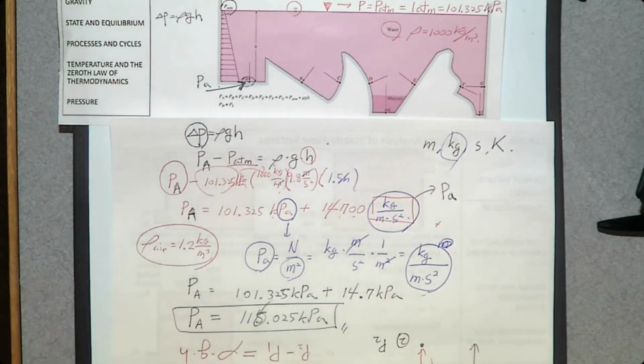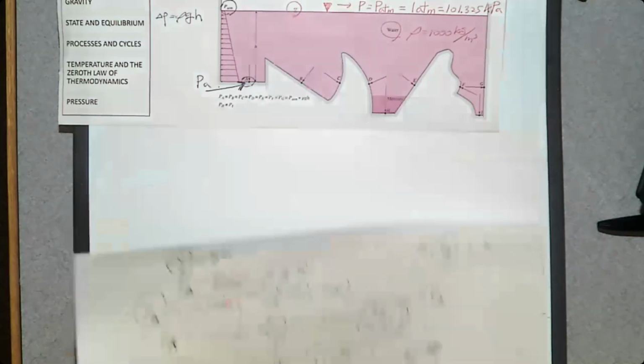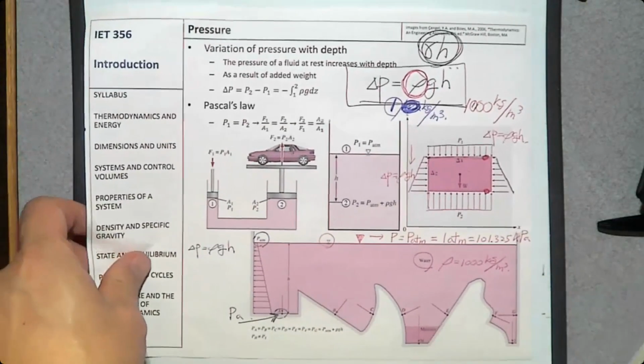So if you consider pressure change in air, this density value is too low, so we don't experience large variation in atmospheric pressure because of the low density. That's why you can climb Mount Everest, but you cannot dive into the water only 20 meters. You cannot breathe because the pressure increase is very significant. Okay. So that's everything about this slide.